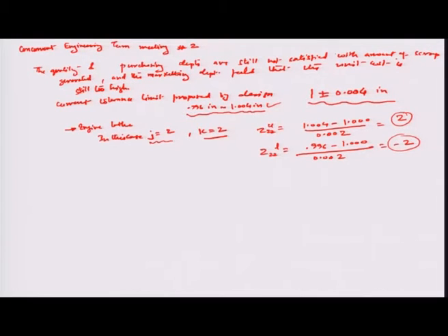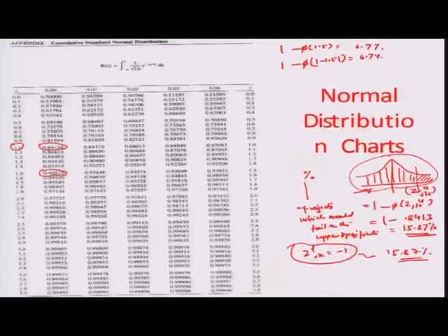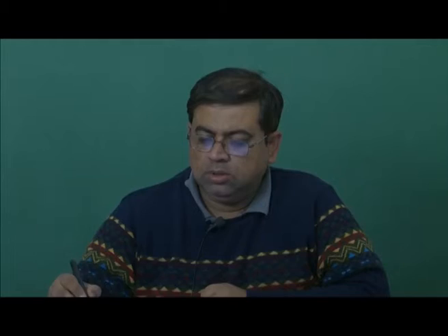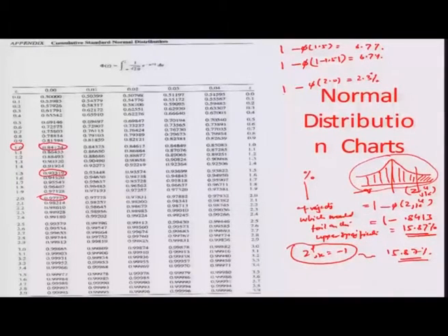With 2 and minus 2 in mind, when we talk about the percentage rejects, again if we can go back and have a look at what the rejects would be in this particular case. With 2 on board, we have almost 0.97725, which means that 1 minus phi of 2.0 would in this case be close to 2.3%, and for the left-hand specification it says again 1 minus phi of the modulus of minus 2.0, which happens to be another 2.3%.